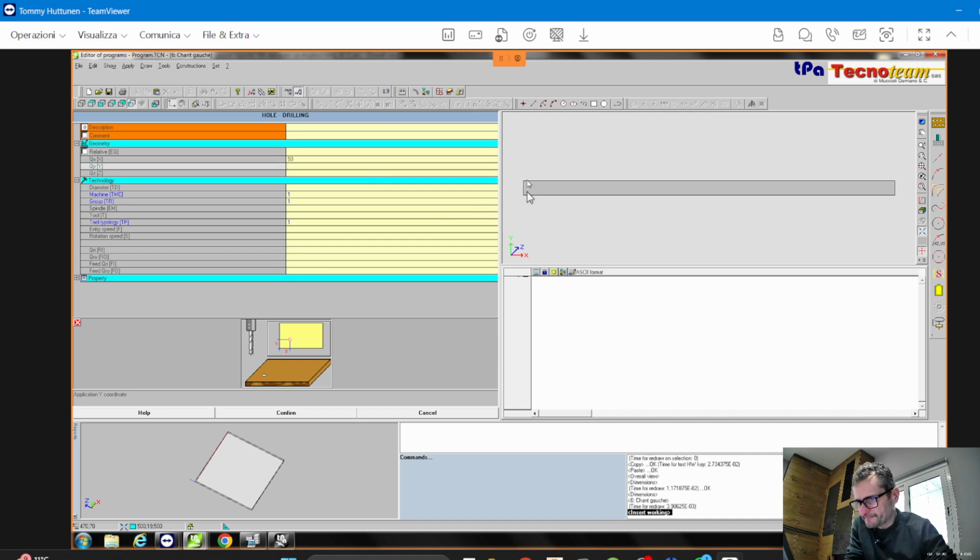This is Y. We know that this is the thickness of the panel, but for the machine this is Y. So if I want to put the hole in the middle, and I want every thickness to be in the middle, I can write it in this way: HF, the height of this face, divided by 2.